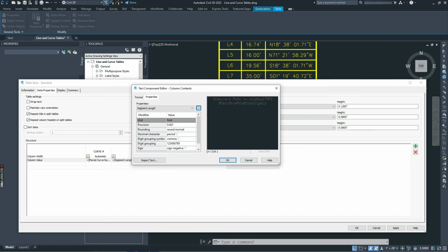And when I go into my composer here, I see that it's the segment delta angle, which is what I want. I am going to try to change the format of this, though, from degrees to degrees, minutes, seconds. So I'm going to click on decimal, hit the drop down here for format, and I can change it to degrees, minutes, seconds. And I don't particularly want to see even the 2 decimal places on the seconds. I don't really care if there are any spaces in there.